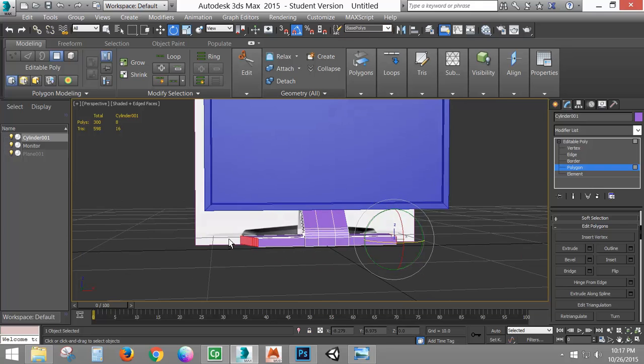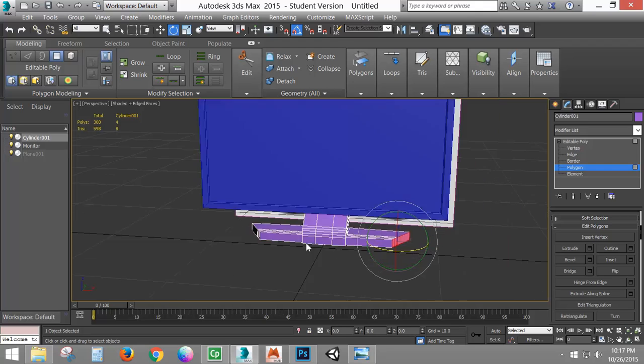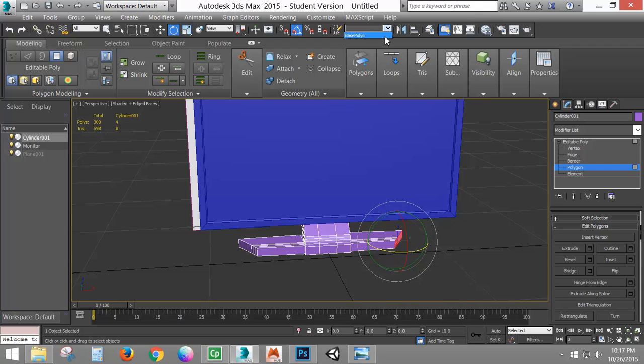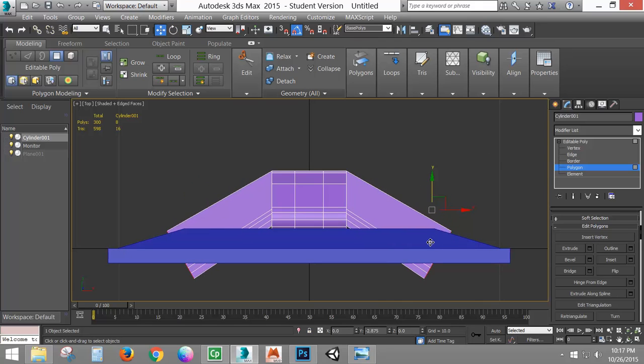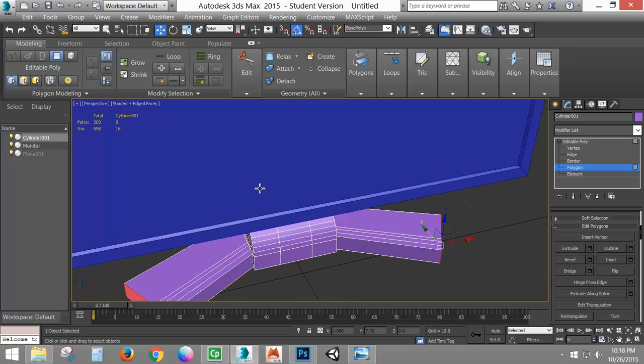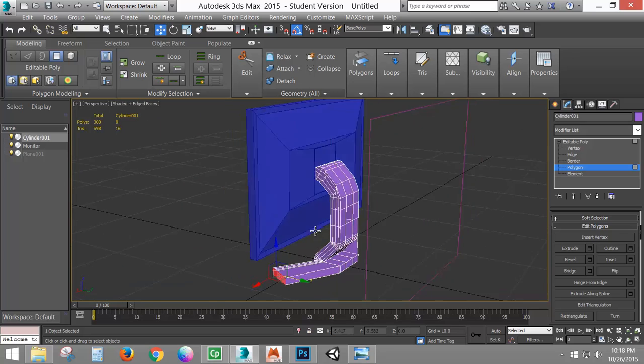Now I can come back up here and say base polys. It's going to select both sides. I'll deselect that side, 30 degrees, and now I'll go to base polys. I'm going to go to the top view, go to move, and I'm going to drag these forward until this kind of looks like it makes a 90-degree angle between these. Okay, that's my base.